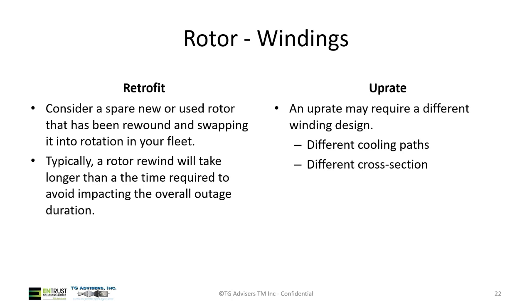So one thing to consider is the option of replacing just the center section of the stator, or some OEMs offer, they'll take the top half off of a small unit and replace the core and the windings as a package.